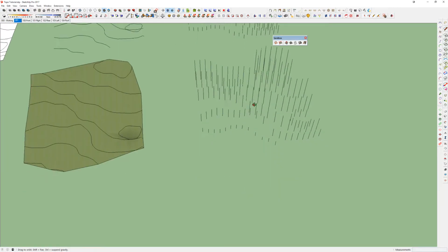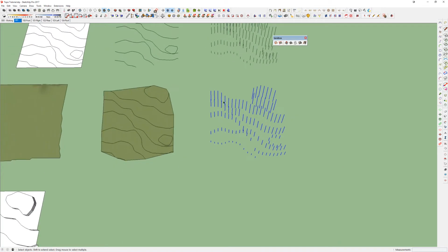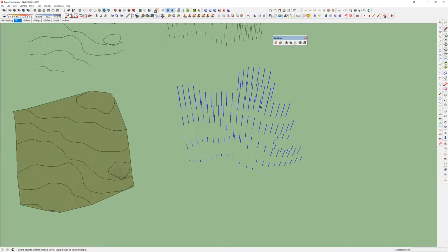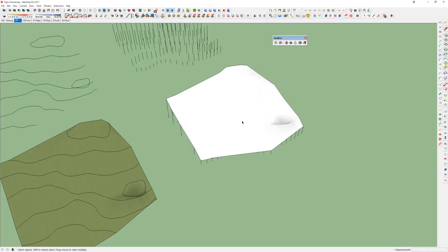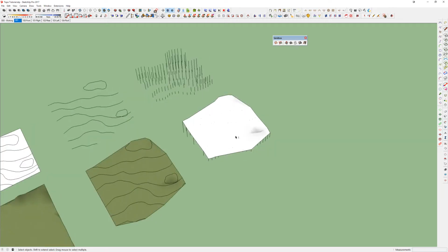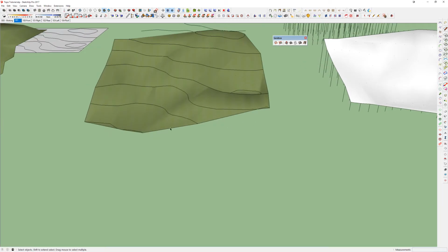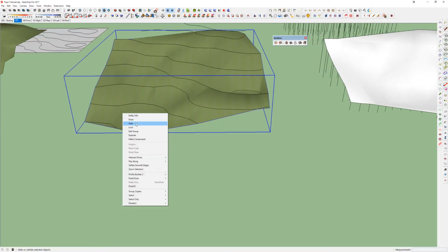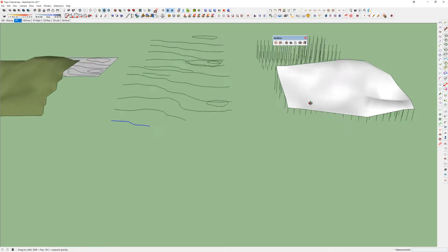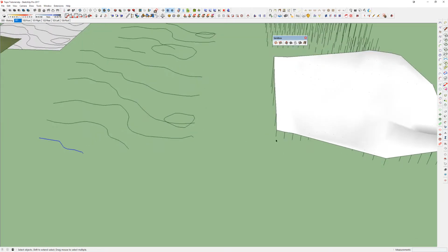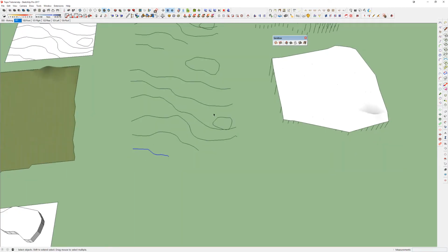And this should give me the exact same result as what we did here, because it's really just going to take these individual points and try and connect everything. So again, using our Sandbox tools from contours, there we go. This one doesn't have this particular, let me hide this line, because this line was at 0, so there were no dots for it. So I guess you could really add those back in, add it, say, a foot, and then lower it back down or whatever.